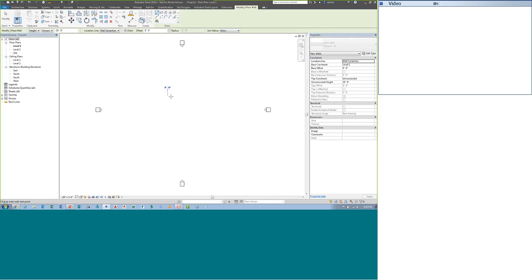First off the bat is we have temporary dimensions that pop up. This is just like dynamic input in AutoCAD. So as you drag and move your mouse, you'll see heads-up display data of the dimensioning of the entity. So if I type in 25 and I hit enter, it gives me an object that's 25 feet in length. Okay? Or I can just move my mouse in the direction that I want to go and just click, and it starts to build that object.